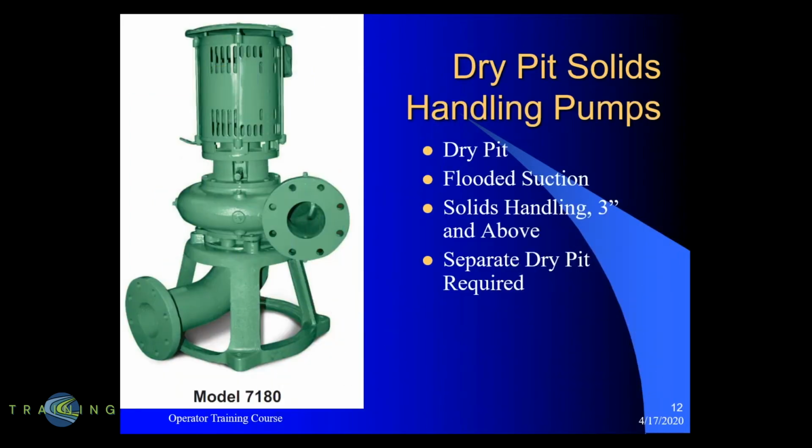Dry pit pumps are also a non-clog pump, but they're designed to sit only in a dry pit. They cannot be submerged. You used to see these a lot more in the past, but now most people are using submersible dry pits. As you all know, especially in our geographic area, if you're in a pit and it's supposed to stay dry, eventually it's going to get wet or flood. So we don't use these very often anymore unless they're inside of a plant. Usually you'll see us use the dry pit submersibles.